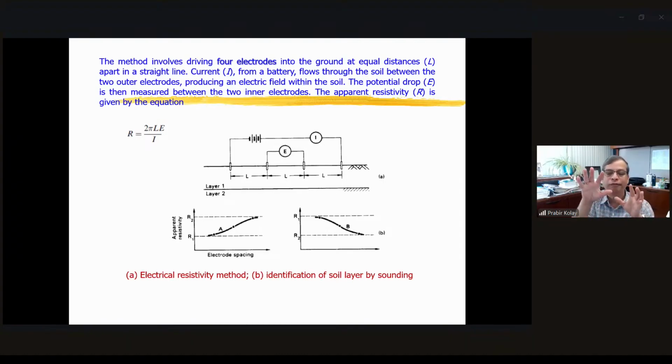If you have more confidence in your bore log, then you can design your foundation or any infrastructure more economically. Most of the time in geotechnical engineering, if you don't have confidence in your data, you use a higher factor of safety. It may not be economical, but in most cases with geotechnical structures, we don't want any failure. If it fails, it is a problem, right? There are methods to rectify it these days, but they are much more expensive.